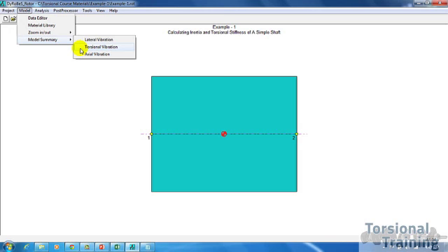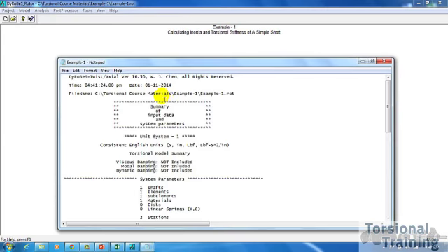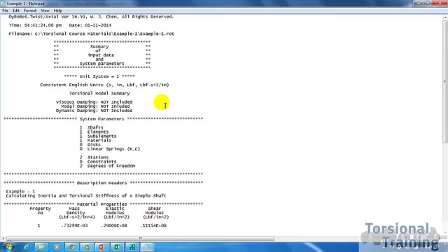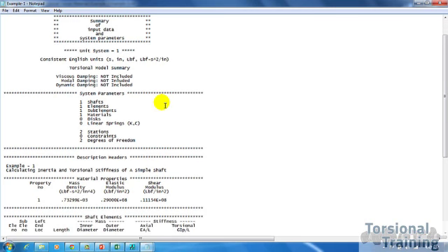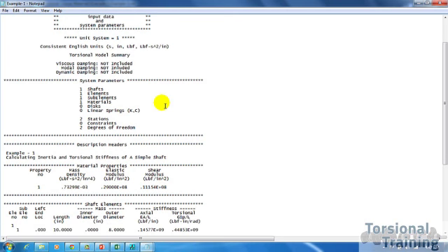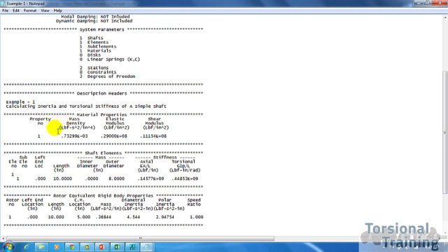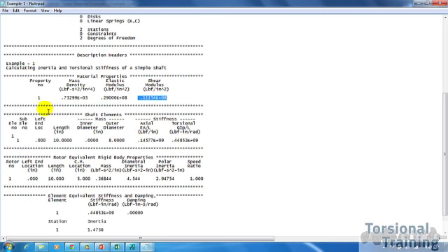So go ahead and click on torsional vibration, and it'll pull up this OT0 file. It's a text file that describes all the different parameters of the shaft that we just modeled. For example, we have material property number 1. The mass density is this right here. The shear modulus is presented right here. We have one shaft element which is reflected right here, and you can see that we have a length of 10 inches, an outer diameter of 8 inches. And so Dyrobes went in and calculated your axial stiffness, and it calculated your torsional stiffness. And this number right here is your torsional stiffness.